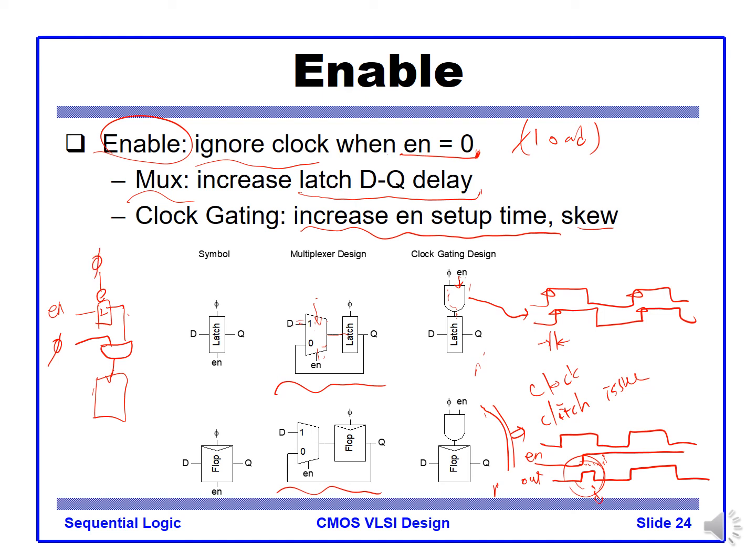So enable only passes when the clock is low, then this clock enable signal will be activated at that time, right? When the clock goes low, then the output clock will be cleanly generated, with no glitches. So this kind of gating clock cell must be available if you want to gate the clock nicely.